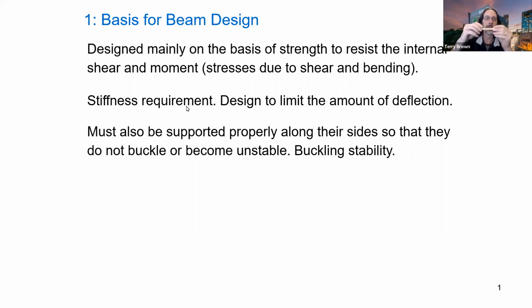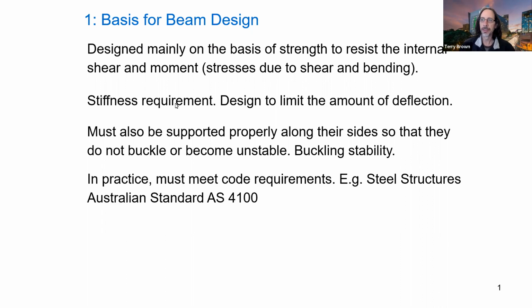But if we have a beam that's this kind of shape and we put a load on it, it can sort of have out of plane deflection, right? You may not be able to see that very well, but you get lateral deflection due to a kind of buckling, right? But we won't deal with that in this subject. That's just a note, I guess.